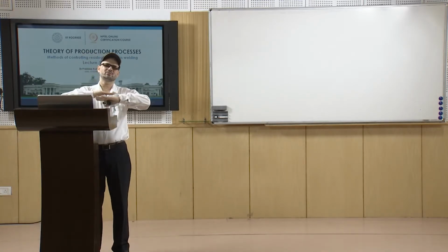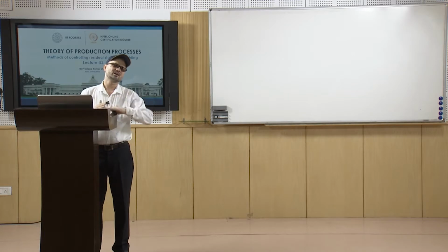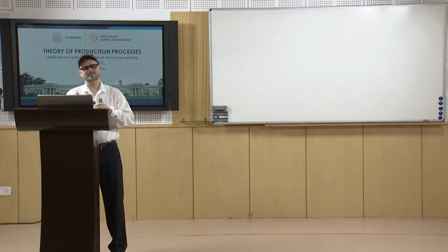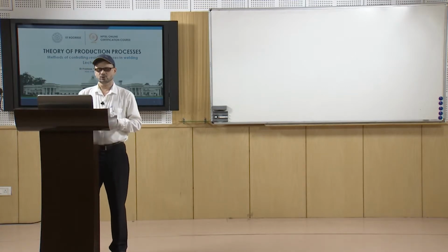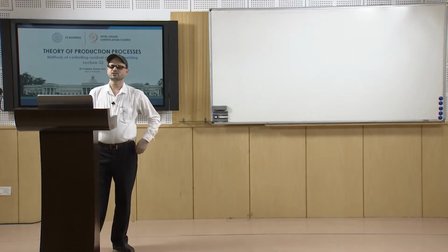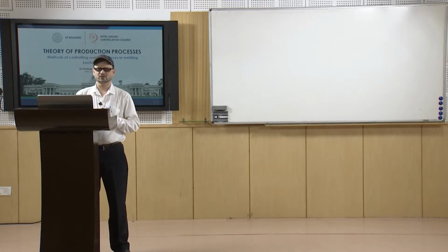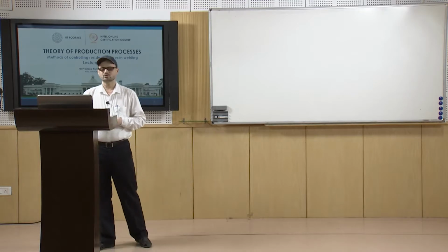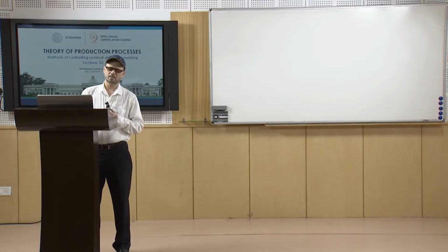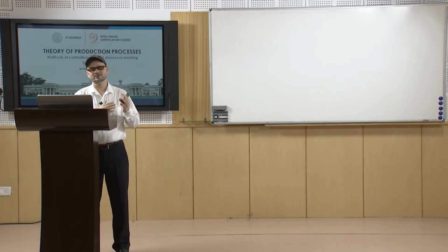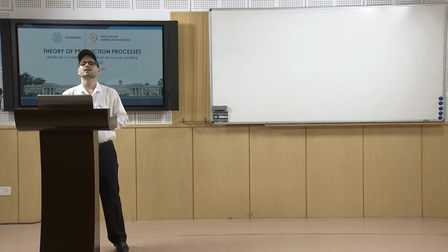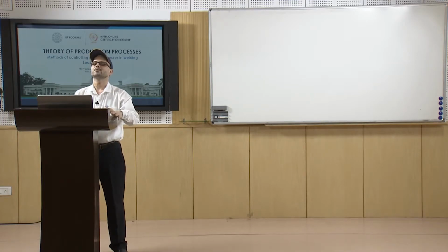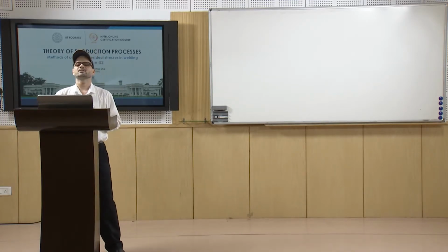If you do it while the metal is very hot, that may affect the weld metal, because there is no subsequent application of heat to anneal that last layer. So, we do not peen the first as well as the last layer. This is an example of peening.